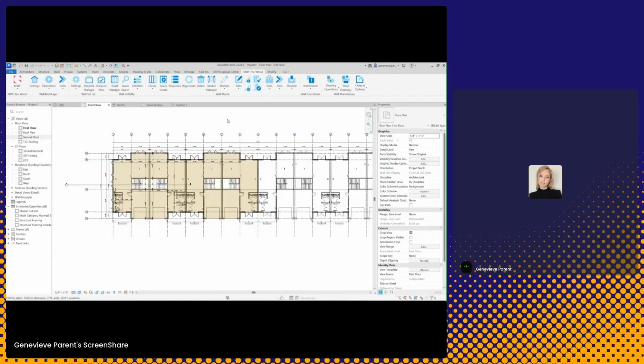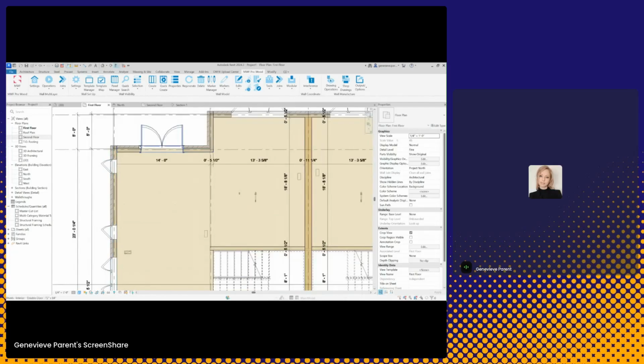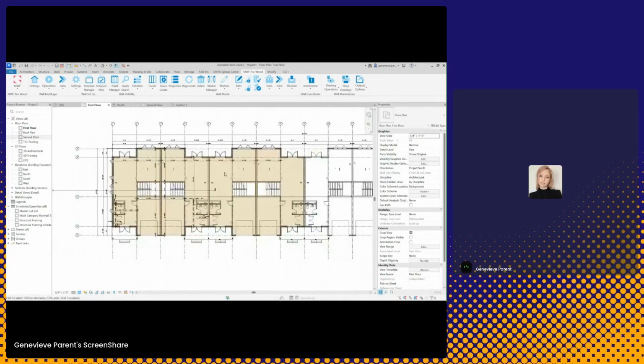And before I go too far, I want to make sure all of my join configurations are already put in. That's another very important part of this process. Since I already have join configuration set up, all I'm going to do is click Auto Join. I already have my rules set up, and this is how we would ideally want to use this tool.